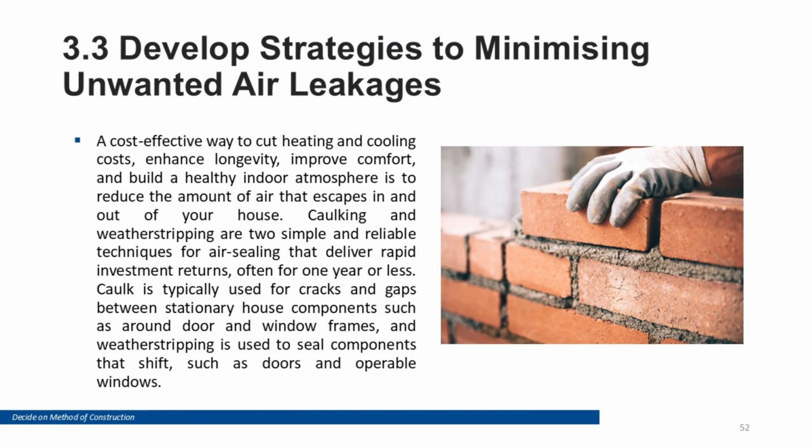Develop strategies to minimize unwanted air leakages. Air leakage control is one of the fastest ways to lift performance. Use caulking, weather stripping, sealants and gaskets to maintain continuity at openings and penetrations. After reducing leaks, provide controlled ventilation to manage humidity and maintain fresh air, especially in high-performance buildings.